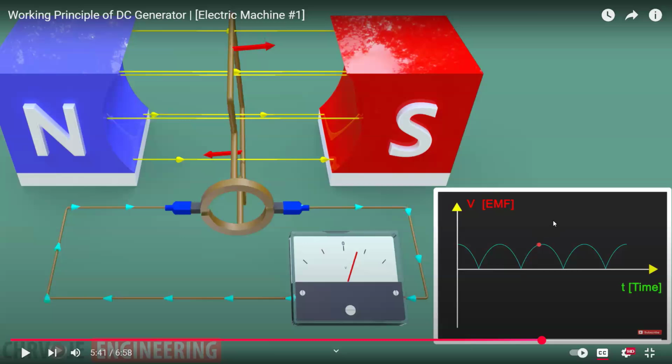Rectified DC volt. Okay. Take care that this is the polarity and magnitude of the volt due to just one turn. If we have many turns, this would add the EMF of each turn together because they are connected in series. And again, this is the volt across the outside brushes, not the inside or the commutator side. So this is at the outside of the machine terminal.